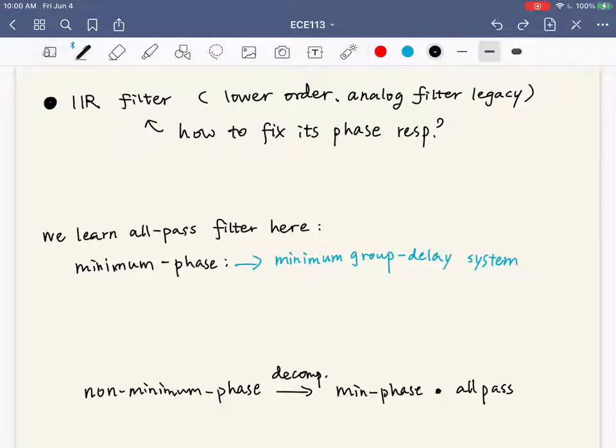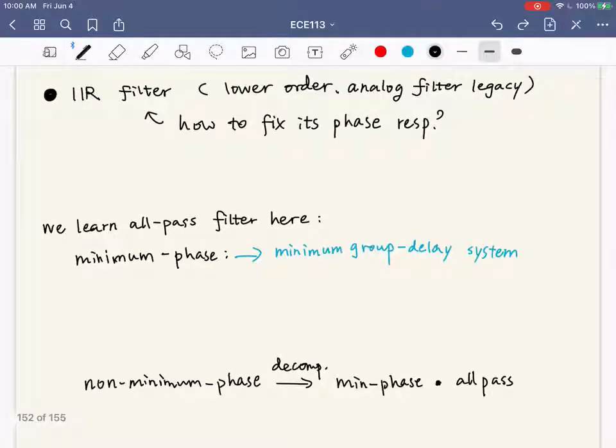Cool. And for the IIR filter, we said that FIR filter has many advantages. Okay, it is by default causal and stable. But why should we still use IIR filter? Here come the pros of IIR filters. First, it has lower order given the same specification. So the lower order means it's easier to implement, and there is less chance to have overflow error, approximation error, and all kinds of stuff.